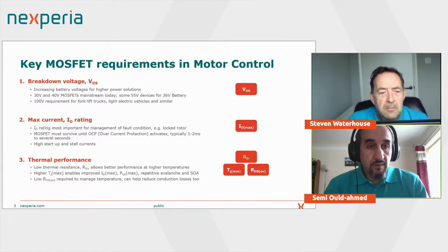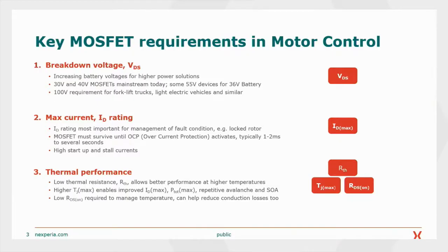The first item selected here is VDS. Perhaps not the fanciest of parameters, but nonetheless, it is the first parameter that one picks for the MOSFET as it needs to fit the power supply of the system. Normally, it is selected so that the supply is about 80% of the rating of the MOSFET. But then again, that's what we see as a trend. If you have another approach, please share with us.